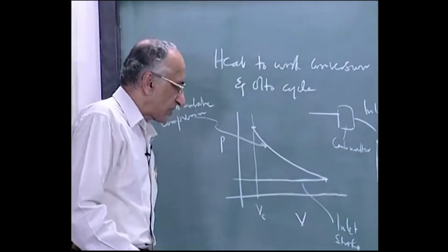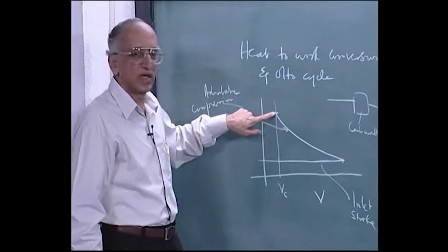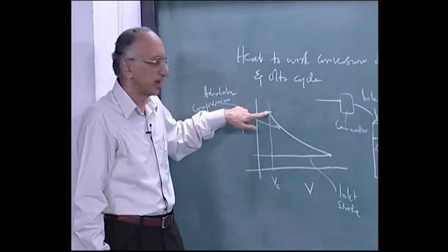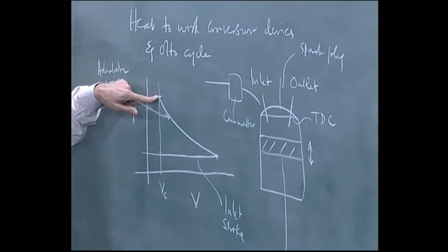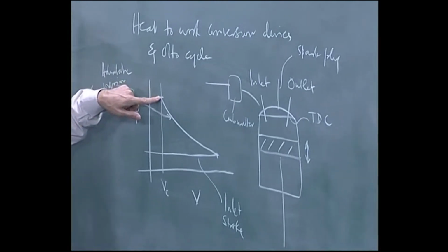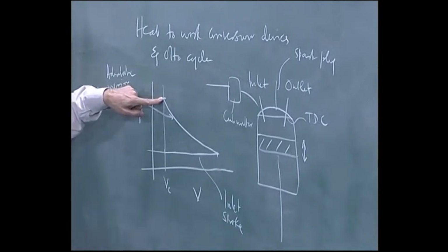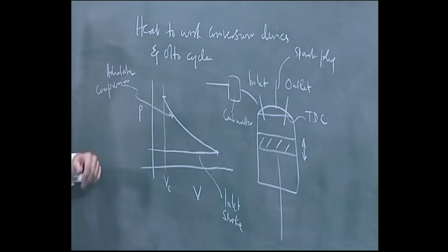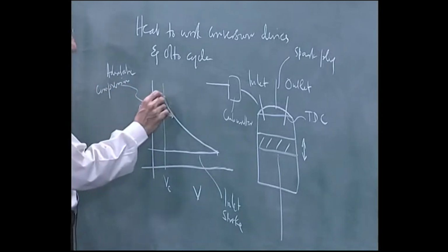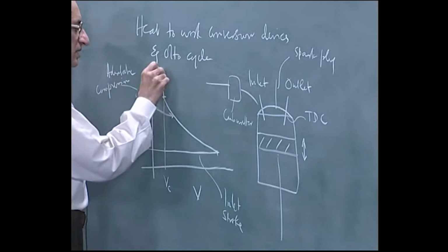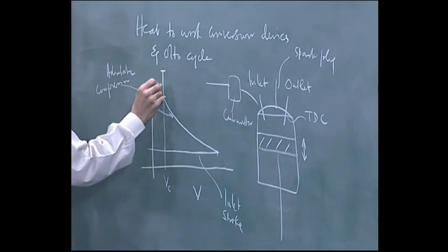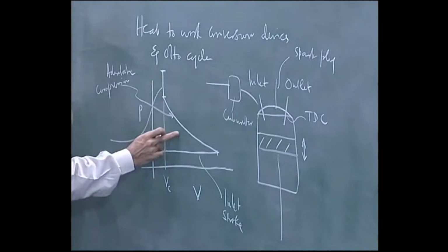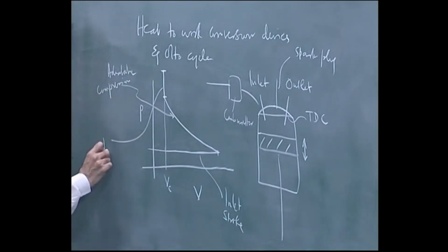Anyway, that is controlled. So at this stage, this is a fuel air mixture, a very small amount of fuel and enough air to combust the fuel, and normally you have excess air because you want the pressure, the fuel is too precious, so you want complete combustion. If you suddenly press the accelerator, you often do not have enough air, so you get a smell in the exhaust. But anyway, at this stage the sparking is done. When sparking is done, in the Otto engine, this is the ignition stage. So this is adiabatic compression, then this is ignition.